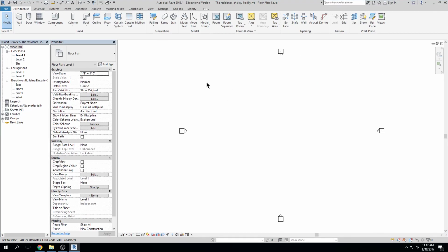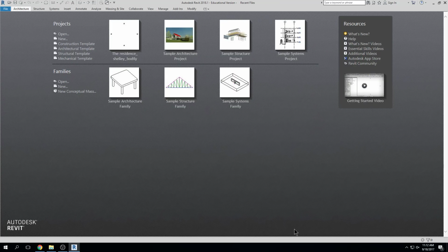One other problem with the backup files that you're going to find, because I've had this problem before, is that if you accidentally open a backup file and then close it out, it's still going to remember that backup file in your history right here. So if you open this up and you think, hey, I just want to open the residence I've been working on, right? If you're not careful, you could open up a backup file from this saved location as well. Warnings all over the place. Don't do it. It's easy to do. Guaranteed you will do it. I have done it before.